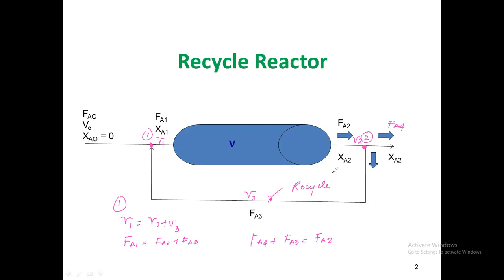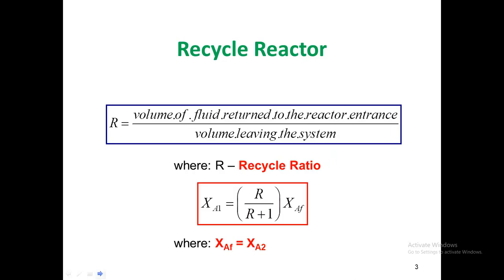So the purpose of the recycle is, of course, to enhance the purity of the final product, or in this case, we use the term recovery, to increase the recovery of your final product. Okay, so that's your recycle reactor. Associated with the recycle reactor is the recycle ratio.